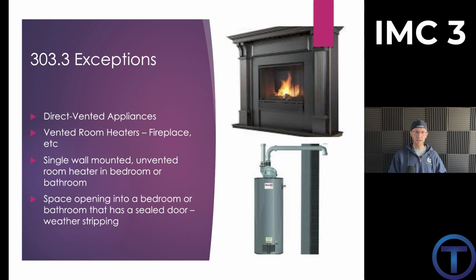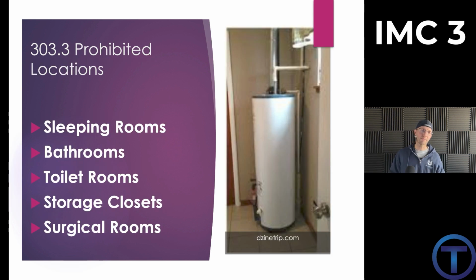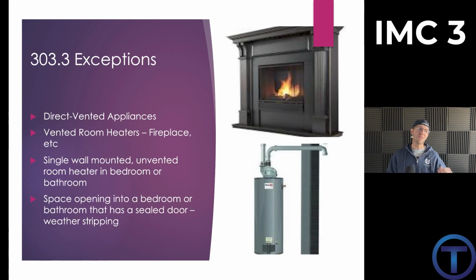Well, it's because the other appliances, we're talking about draft appliances. We're talking about, are you going to be burning up the breathable oxygen in that space in order for this appliance to function? And if so, let's not put them there because I'm sleeping in this room and I don't want to die. But these appliances, the exceptions, don't create that same level of risk. Direct vented appliances are going to be drawing air from somewhere else. Vented room heaters or fireplaces don't draw enough air to create a hazard in that way.